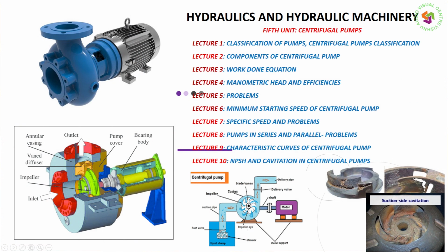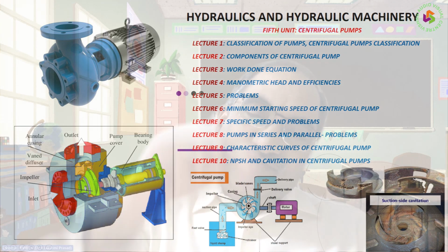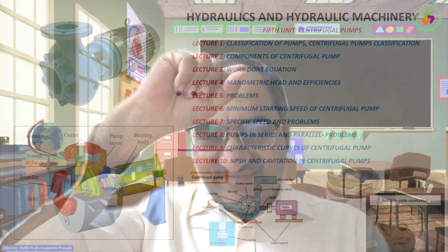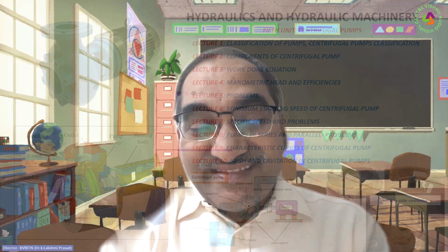Suppose the water is there in the well. The vertical distance from there to the inlet is what we call the suction head. So what shall be that maximum suction head? Suppose we go on increasing that, will the pump lift?